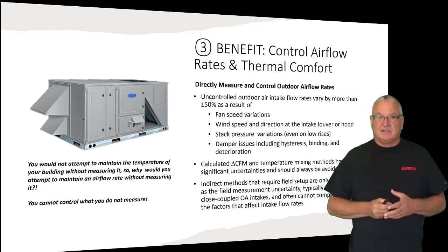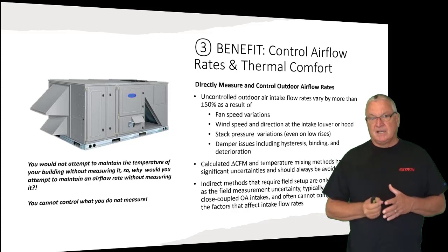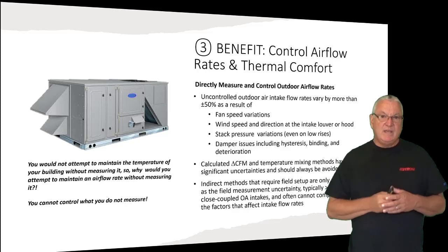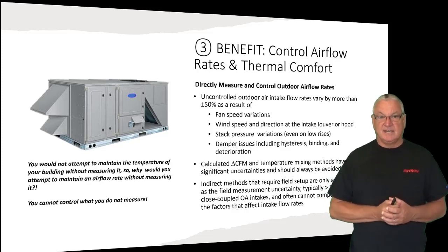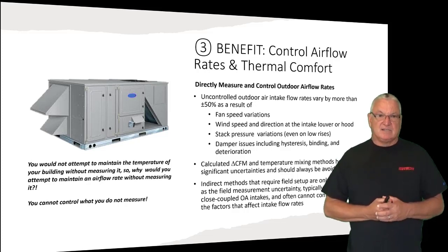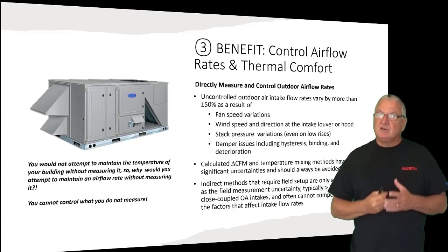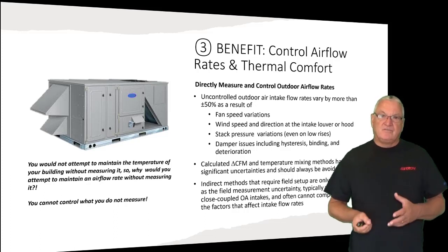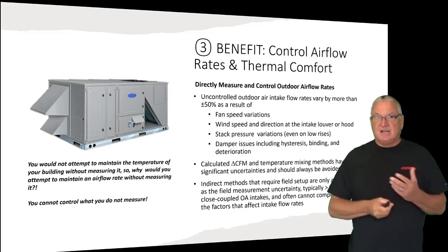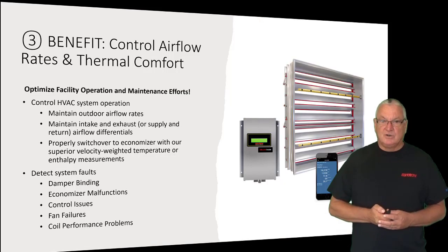All the indirect methods, there's a lot of methods out there right now, require field setup by test and balance. And it's nothing against test and balance folks. We have a challenge of measuring in a lot of these outdoor air intakes. Test and balance professionals have even a greater challenge. Sometimes they have to measure outside of the unit and the flow rates are very low. It's very difficult to get accurate measurements, and because of that, these field adjusted or field calibrated techniques can't be any better than what they're calibrated to. So again, we have a nice presentation. If you're interested in this, join us for that presentation down the road.